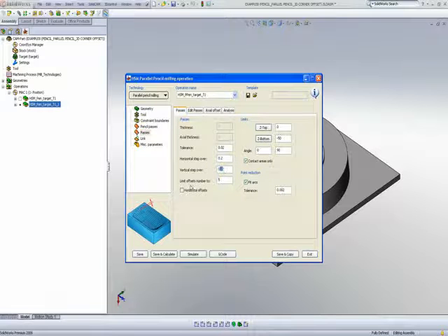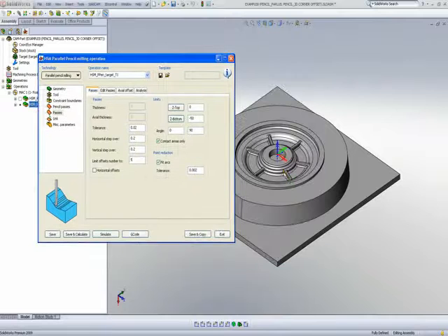And what I can do is I can say, let's limit it to only 5 steps past the part. In other words, if I'm going on a specific pencil boundary over here, it'll only go 5 steps of 0.2 millimeters outside.